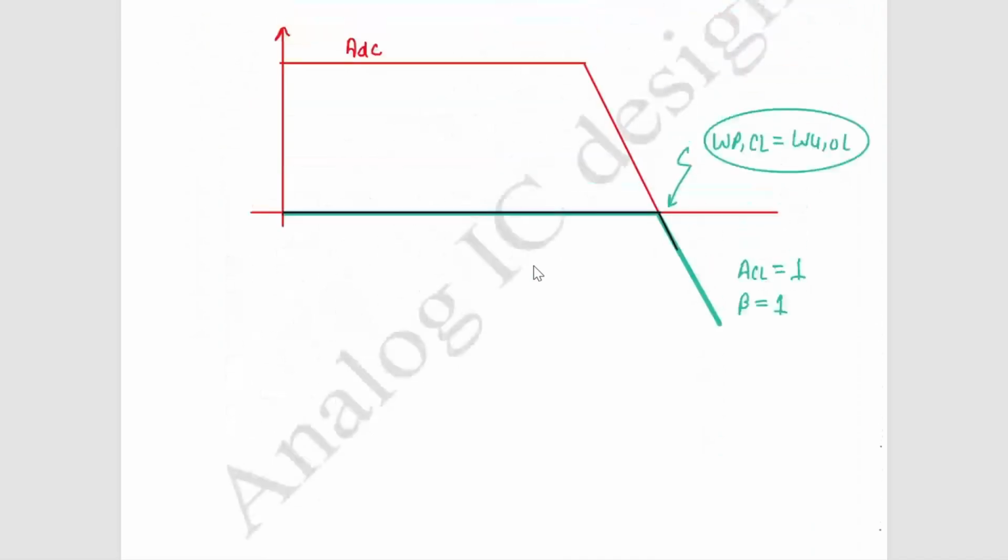And for second order system, gain bandwidth product will not be equal to the unity gain frequency. Okay, so suppose here you see one more pole location. You calculated gain times bandwidth, you are supposed to cross here, but in between you get one pole, and now you are pulled down another 120 degrees. So your unity gain frequency is exactly this one, but you had calculated this one. Okay, so in that case, your unity gain frequency will be lesser than gain bandwidth product.